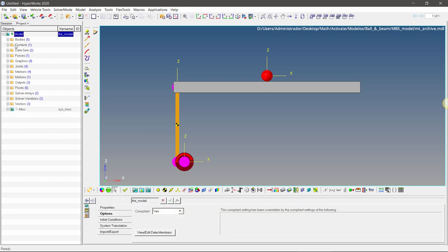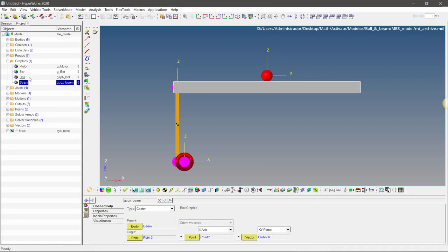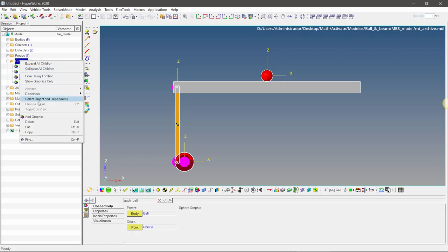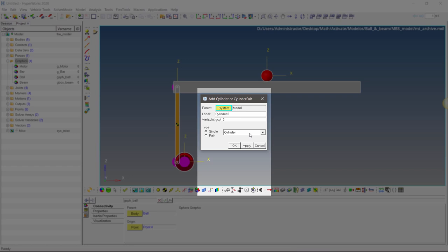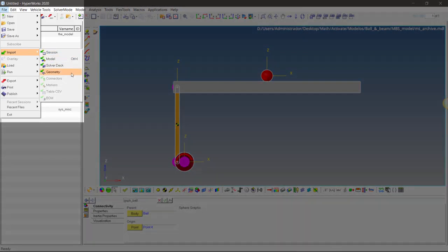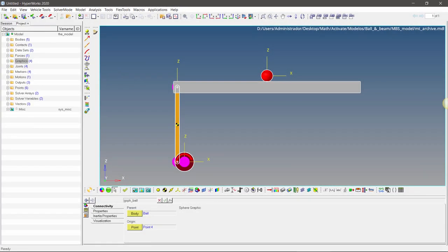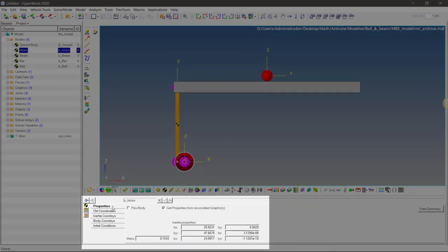In MotionView, it is possible to create some types of geometry graphics to associate with the bodies. Since this model is composed of simple geometry bodies, all components can be created in the interface itself, because they are cylinders, balls, and boxes. Otherwise, it is possible to select a CAD geometry as well. Once we have the created bodies, it is possible to associate their properties or select to calculate them automatically from the geometry graphic created.